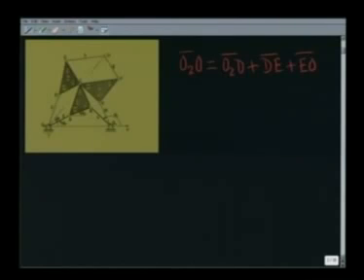Similarly, O4BCG, that is also a parallelogram, and OECF, that is another parallelogram. That means, the link AC is same as the link O2D, link length EO is same as the link length CF, and so on. Not only that, the 3 ternary links, namely link number 3, 6 and 9, these consist of 3 similar triangles as indicated by these 3 angles, namely alpha, beta, gamma in each of these triangles. So, these 3 triangles ABC, CGF and CED are 3 similar triangles.